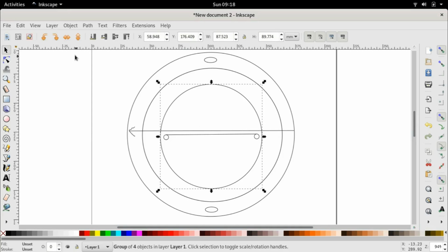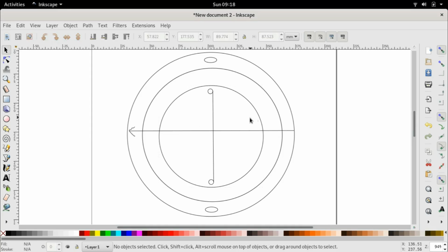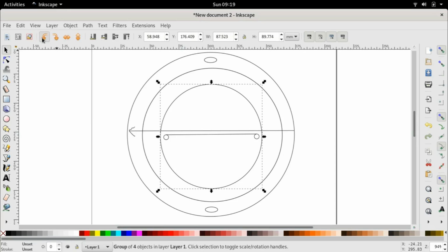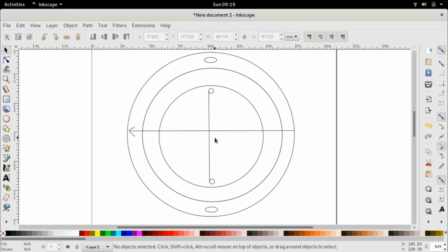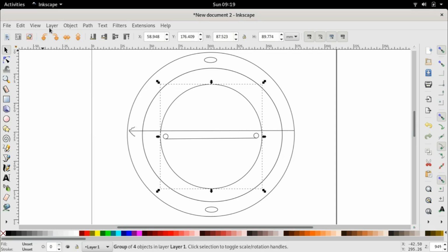So, in this position, the linkage of the stator flux with the rotor is maximum. In this position, 90 degrees apart, the linkage of the stator flux with the rotor is zero. And we can keep rotating also, right? So which means that here, the linkage of the stator flux is back to maximum, and once again, it is back to minimum. So you can see here that there is some kind of a sinusoid which is happening. Now, let me ungroup it again.